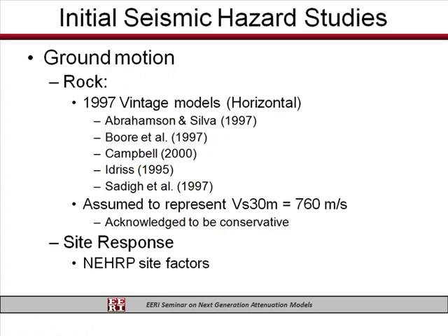For the site response analysis in the 2002 model, what they did as well is they took the NEHRP site factors and just applied those to the reference motions of the rock at 760.